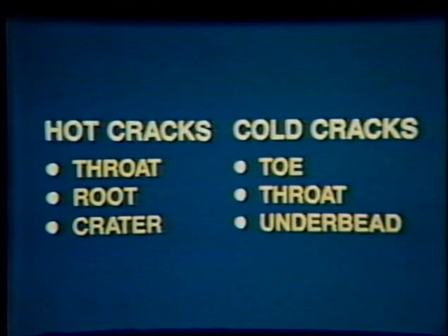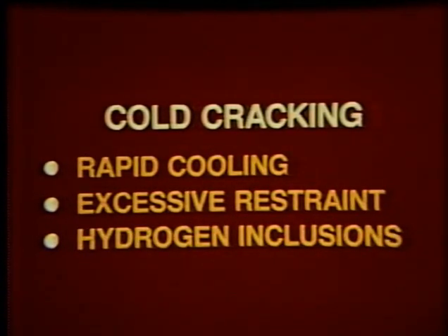The second type of cracking is called cold cracking and occurs after the weld metal solidification is complete. They may appear as toe, throat, or underbead cracks and can occur up to several days after welding is complete. In general, cold cracking is caused by rapid cooling of the weld and heat-affected zone in higher carbon and alloy steels. Excessive joint restraint and inclusions of hydrogen in the weld also contribute to cold cracks. These factors must be considered collectively when determining the cause of cold cracking.